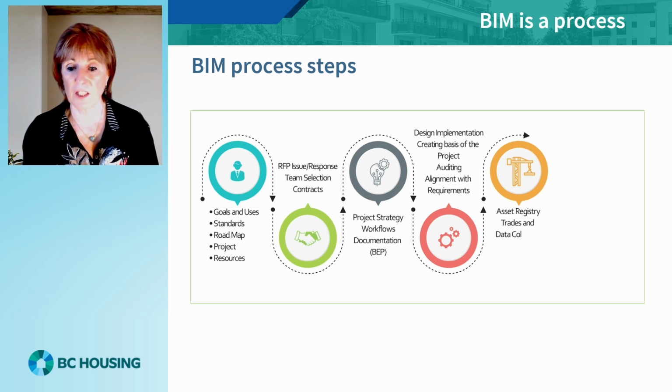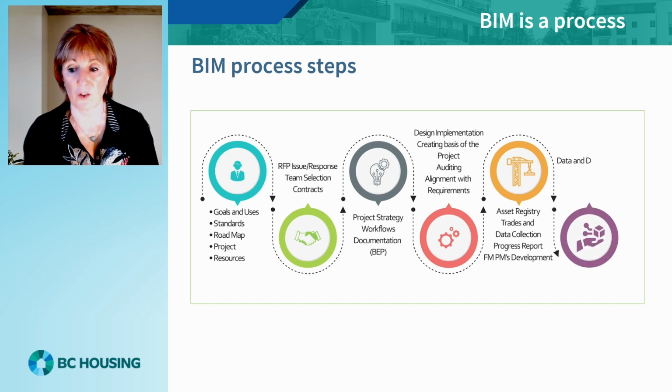At the end of the design phase, the project dataset is sufficiently robust to enable the generation of an asset registry. This is a list of all assets, rooms, or other information that is required for management of the project during its life cycle. During the construction phase, required installed asset information is linked to the design intent information, providing the facility team with the opportunity to start development of their preventative maintenance plans prior to handover.